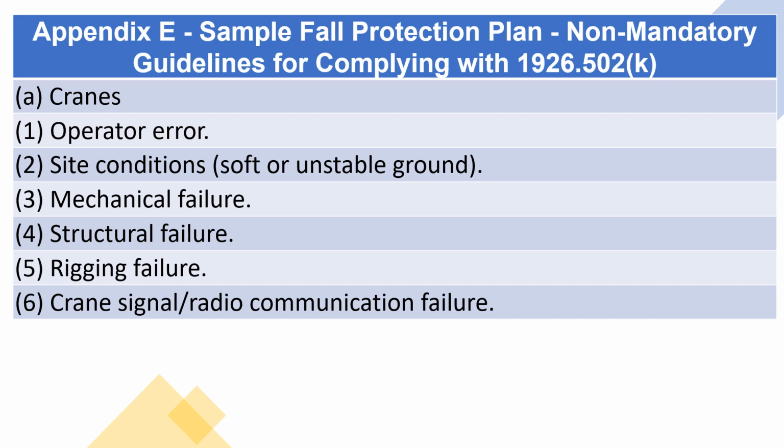A. Cranes. 1. Operator error. 2. Site conditions, soft or unstable ground. 3. Mechanical failure. 4. Structural failure. 5. Rigging failure. 6. Crane signal/radio communication failure.